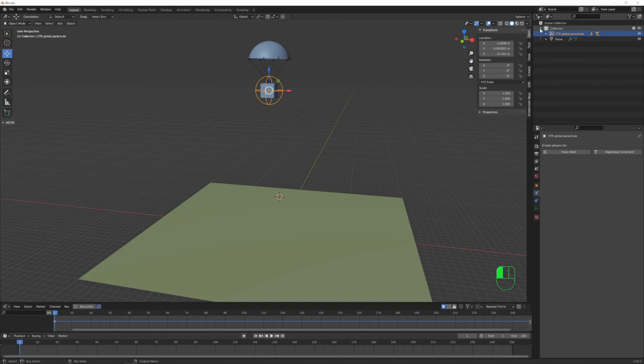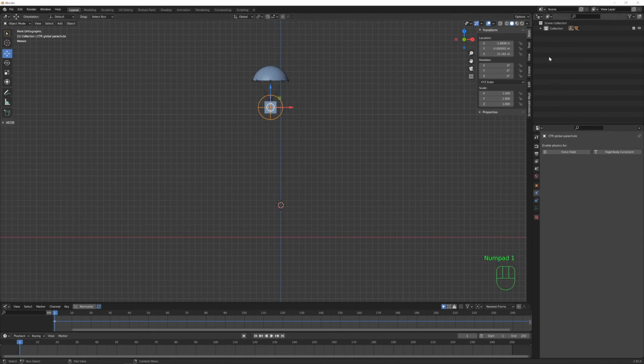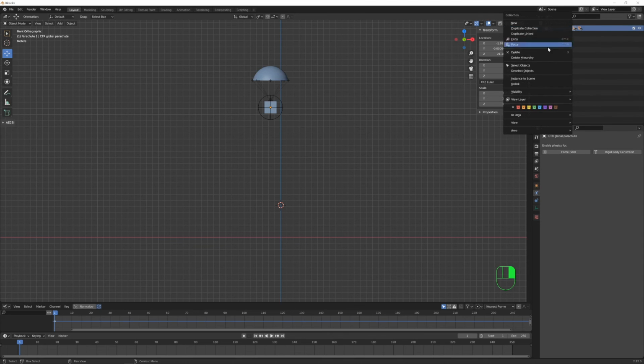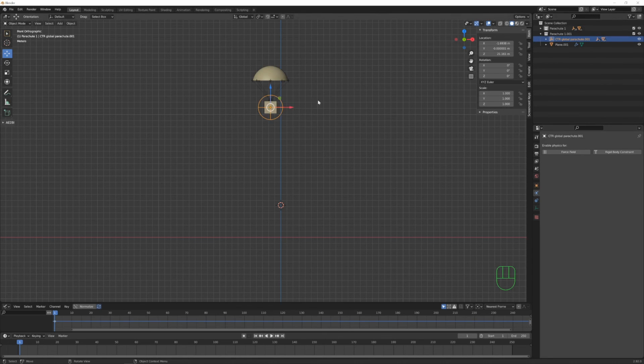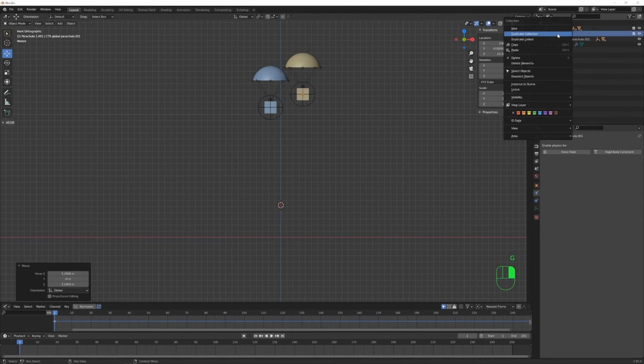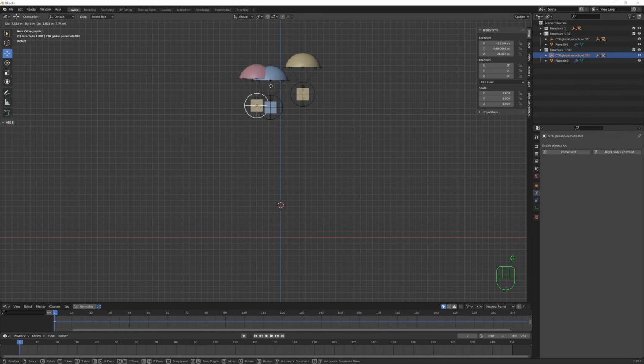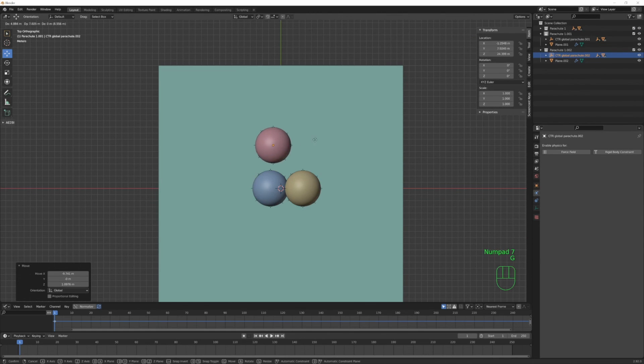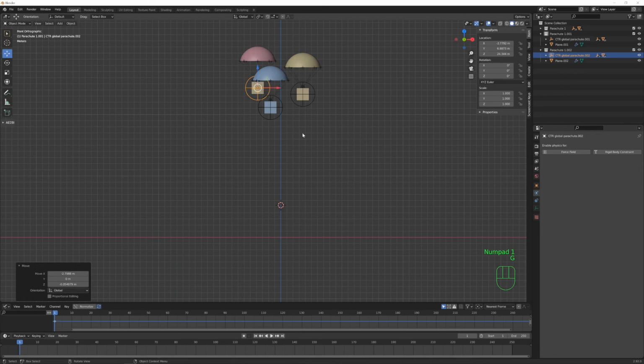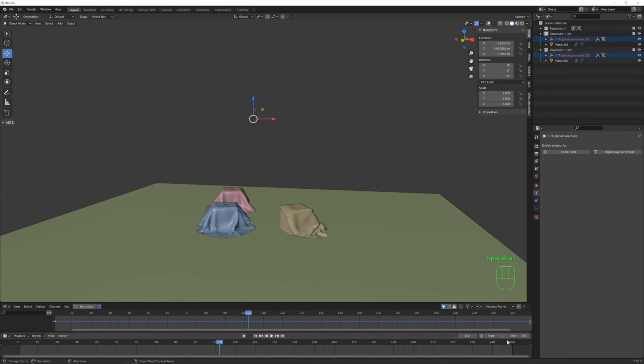And one last thing that's very nice to do is that, let's call this collection Parachute 1. You can just duplicate the entire collection, and you have already another, and you can duplicate another one, and you already have 3 nice parachutes that will fall down together. Of course, the simulation will slow a lot. Okay, let's set the end frame to 100 frames.